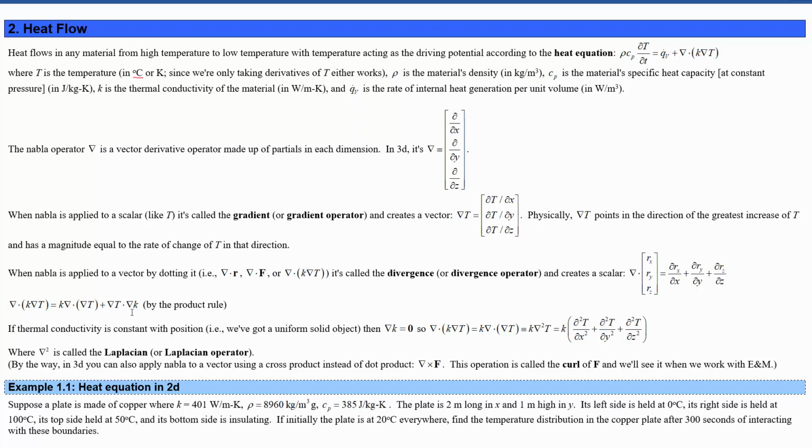So if we have a thermal conductivity which is increasing with position, then it's important for us to be keeping track of this thing, and just going back to this original version of it. But if the conductivity is a constant, you could simplify that by taking the conductivity out of the equation and then rewrite this using the grad squared. So this, Nabla squared, I suppose, is often called grad squared because gradient is quite a common derivative. Sometimes people just call this the grad operator. So if you hear that, that's probably what they mean.